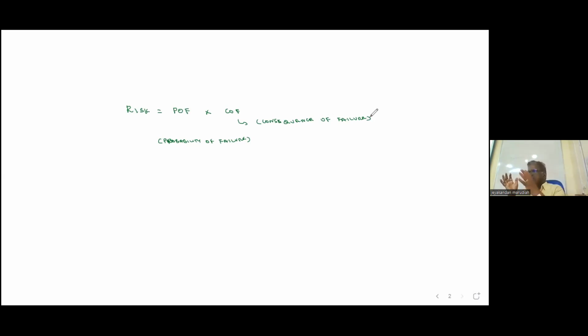So RBI is a separate methodology. If you are going with RBI, we will not follow the 653 rules. You can increase the inspection interval beyond 653 or decrease it based on the risk involved. Risk means, suppose there is a leakage, how it will affect the environment and the public. I will not go into much detail because it is not important for the exam. For 510 and 570, RBI plays an important role.